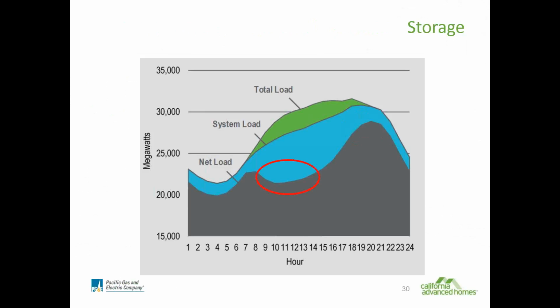But storage is really about this spot now and throughout the day. We should be putting energy into our batteries, filling the batteries up at this time of the day, so that later on in the day you can expel the energy that's in those batteries and apply it at that peak. So it's shifting energy. And battery storage typically won't be storing it long term. It's just storing it through the day. And the net effect, the same thing we saw with efficiency, is you're going to just shave off that peak.